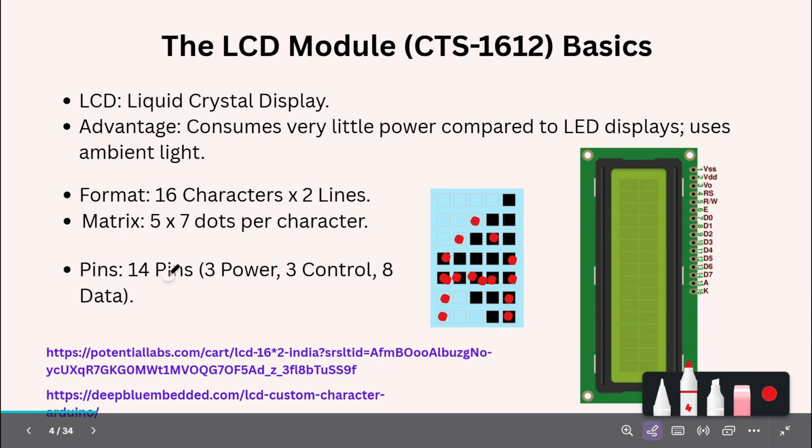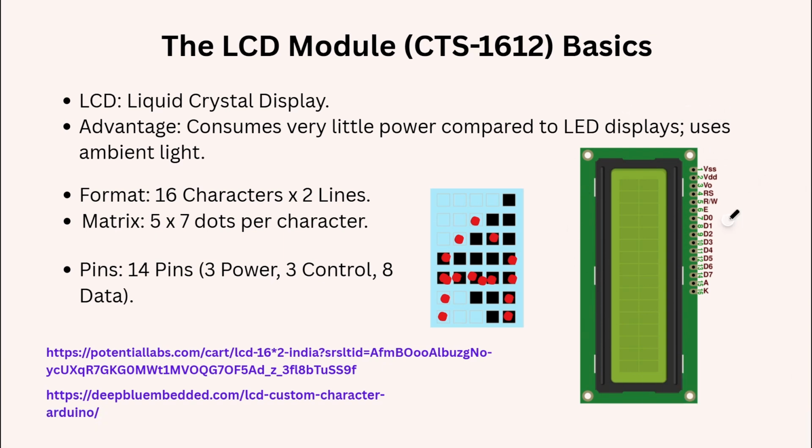So there are 14 pins, which are shown in this diagram. We can see the power pins, control pins, and the data pins. There are 14 functional pins, and then 2 pins are actually for backlight versions. The 3 pins handle the ground, the power supply, and the contrast.